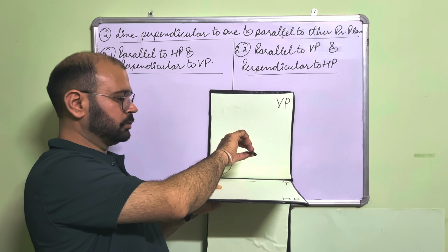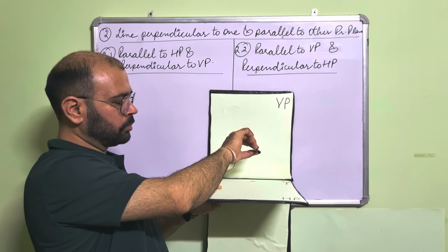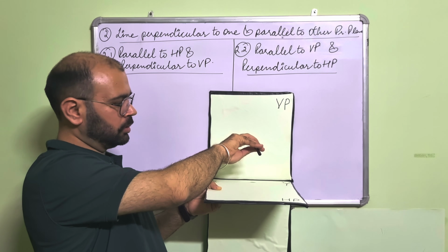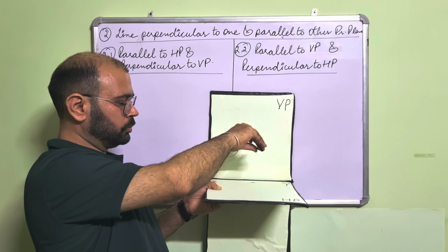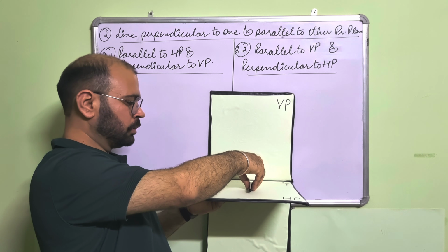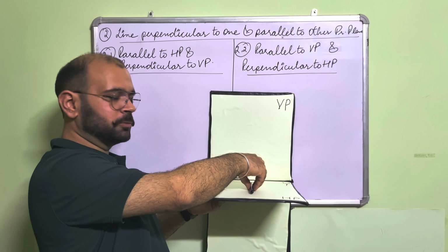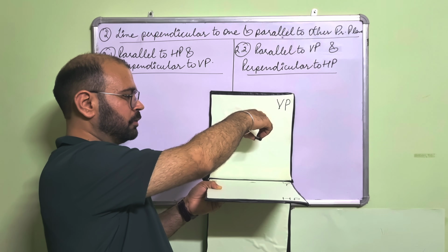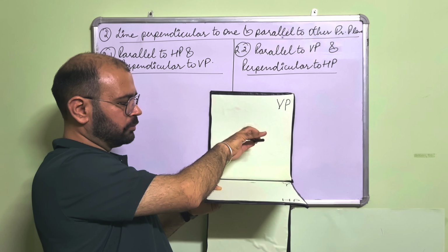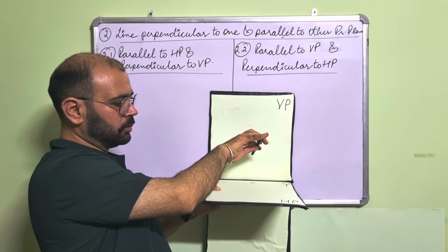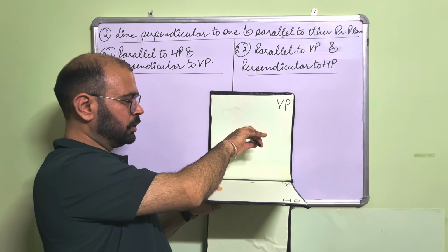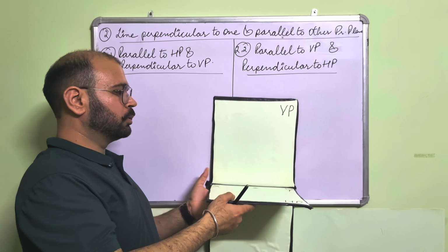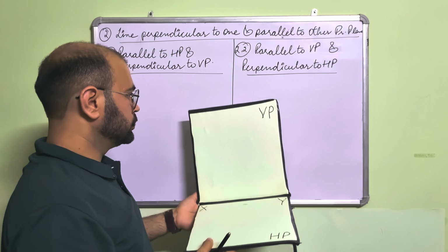So like this it is represented, right? If this is A and this is B, when you view it from the top, it will be a line which is perpendicular to the XY line that is visible to you, and when you see it from the front, it will be just a point. When you see it from this direction, it will be just a point that is visible to you in the front view. Front view will be a point and the top view will be a line.